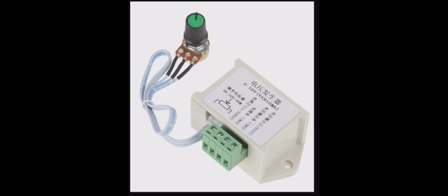For example, 0 to 10 volt DC is prevalent in building control, that is HVAC applications, though it may have some crossover into industrial control. When in doubt, check the specification of your devices to learn about the voltage output range. Every device has specifications. Some operate on DC, some on AC, as per their application.